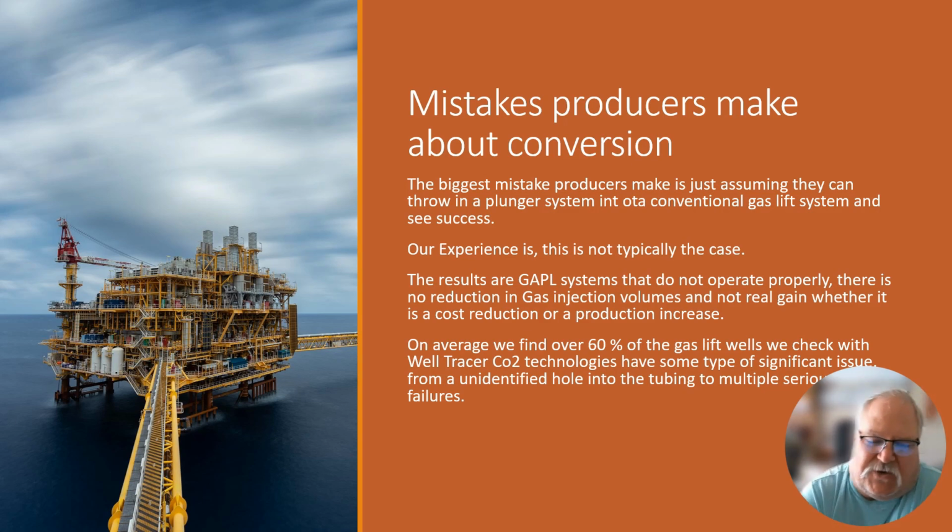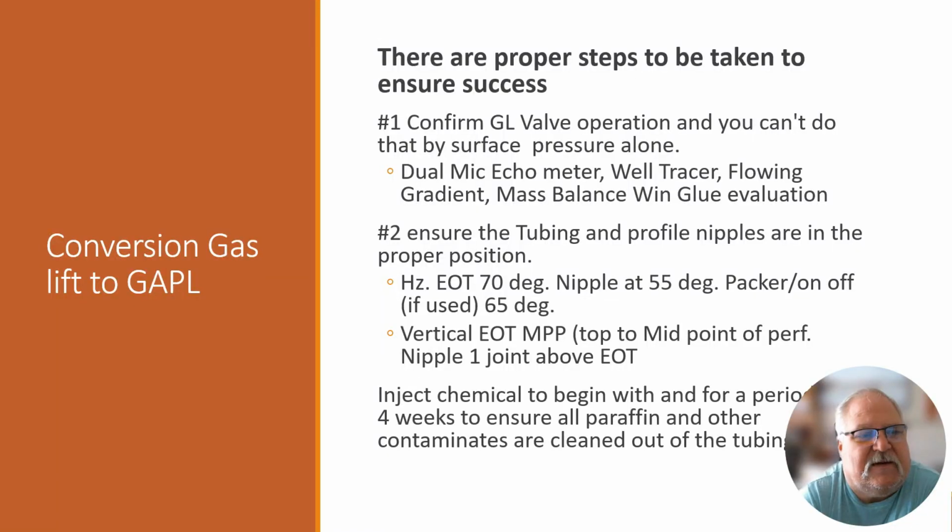If you're still using your old data from your initial design, your surface injection pressure may be the same, even though you're injecting much higher than you think you are. So it's probably one of the biggest things we see, and this is even after just a couple of years: we find a ton of plugged orifices in the bottom, say 300 to 500 meters, of these wells, where scale has built up around the valve and plugged them off.